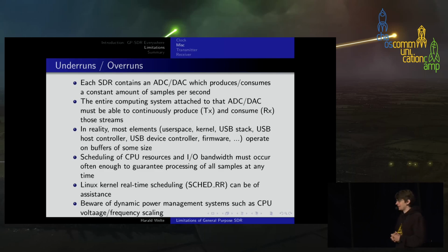So you cannot implement a 3G base station, for example, a real one, with an SDR that's attached over USB, because the latency of USB is way too high. You can never do the timings. And even for LTE, it's actually rather amazing what projects like srsLTE are doing, that they can do this within the stringent requirements of LTE, despite wasting so much time moving data over USB back and forth.